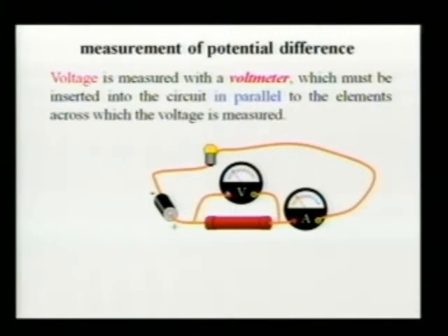By the way, I marked the terminals of meters with red and yellow colors, because when you connect a meter, it says which side is supposed to be connected to higher potential and which side to lower potential. If it is an electronic meter, then it doesn't matter, because the digital display will say either plus 1.5 volts or minus 1.5 volts.